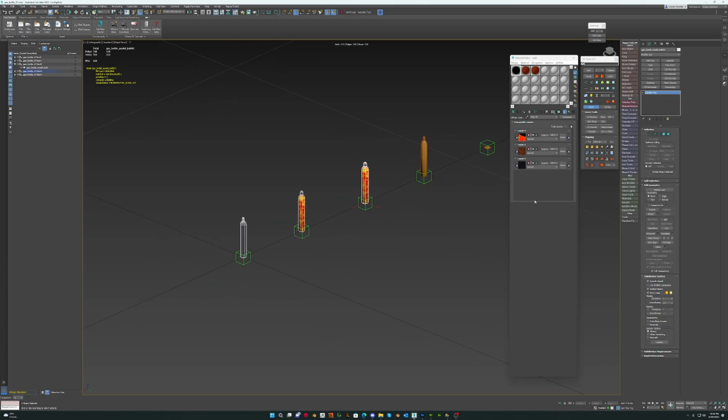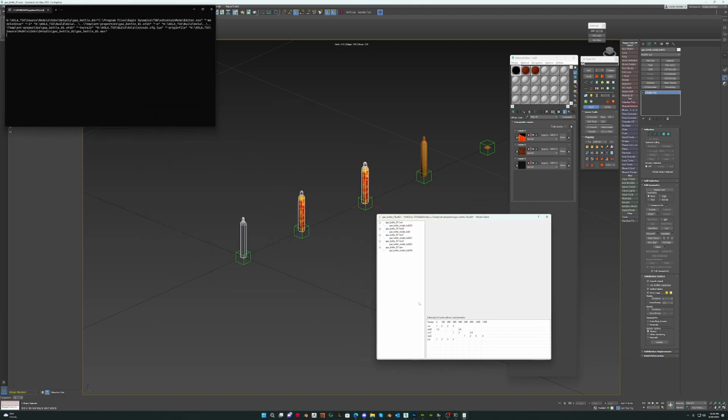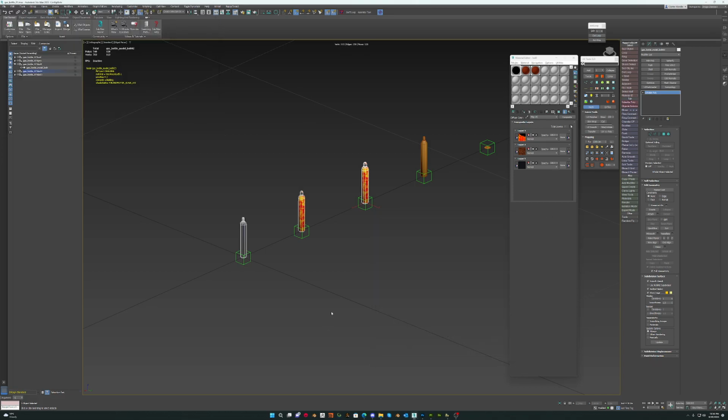So for the LODs, a couple of other things we need to do is that if we go back into the set model properties, if we go into the actual meshes for LOD 1, the only thing we have to tick here is use palette. You do not specify a line number. I do the same for LOD 2, click use palette, and then I close that.